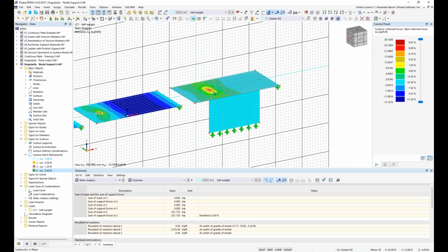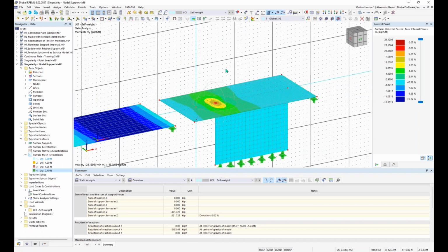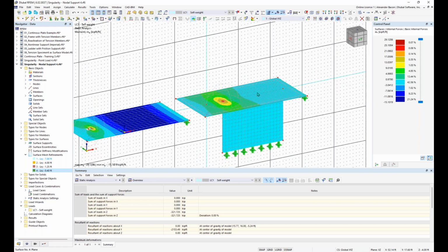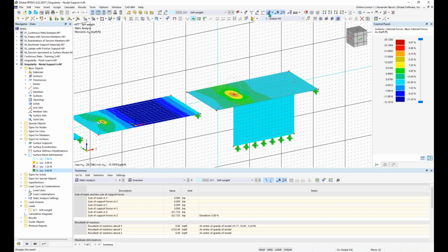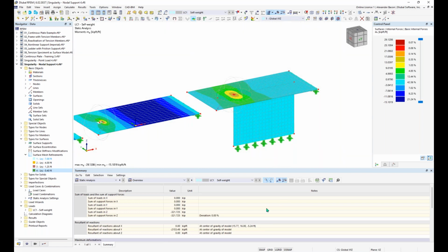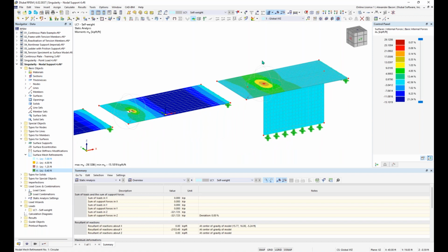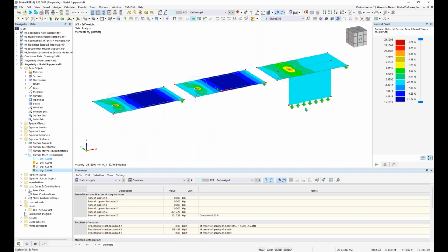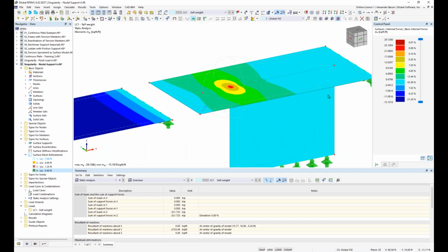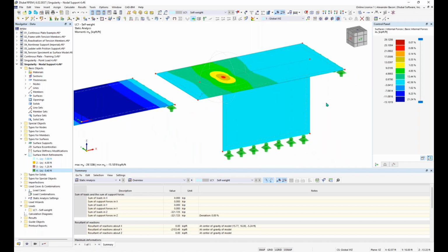So do you mean turning it on and off graphically? Yes, like the squares that are shown right there if you don't want to see that. Yeah. If you want to get a cleaner view of your model and you don't want to see the FE mesh here, you can go up here to this drop down next to the button and you can turn off the display of your FE mesh like so. Okay, yep, that works.